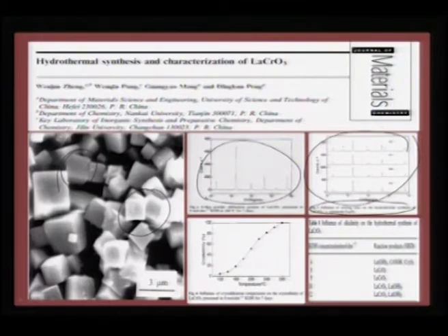So each system holds some surprise, and again there is the influence of alkalinity. If you take potassium hydroxide mineralizer, you would see the critical composition where pH is 8 to 9 is the place where you would really get LaCrO3 in single phase. In other cases other compounds do precipitate. So pH is a governing issue, and then stirring improves the crystallinity, and also the temperature seems to improve the crystallinity to a greater extent for LaCrO3.